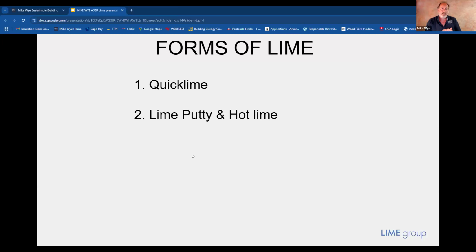A hot lime mix, you could argue in many cases, is perhaps a very historically correct or appropriate way of mixing a lime mortar. As you can appreciate, in times gone by, if you were building your structure, you may have access to limestone, which you would fire yourself. You may have access to quicklime. You would have access to sands, aggregates, and other materials.